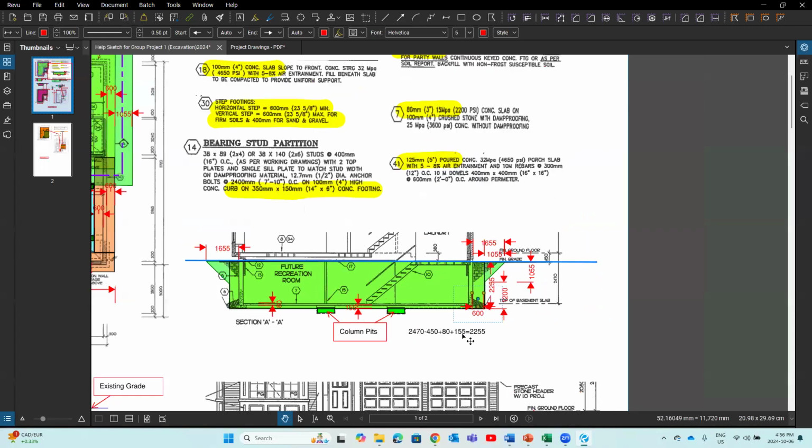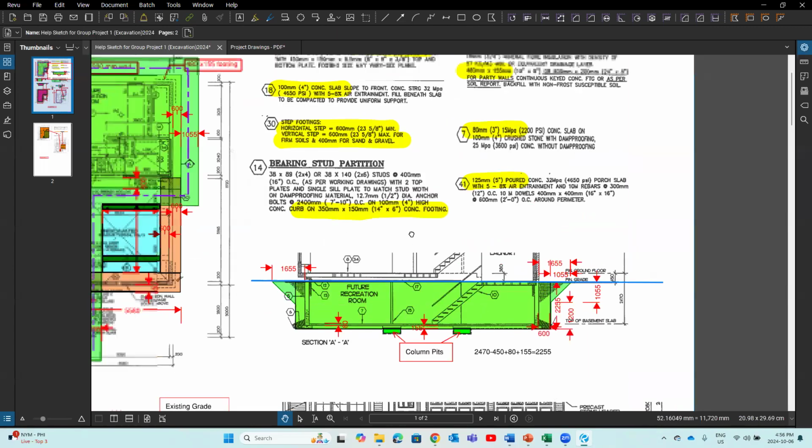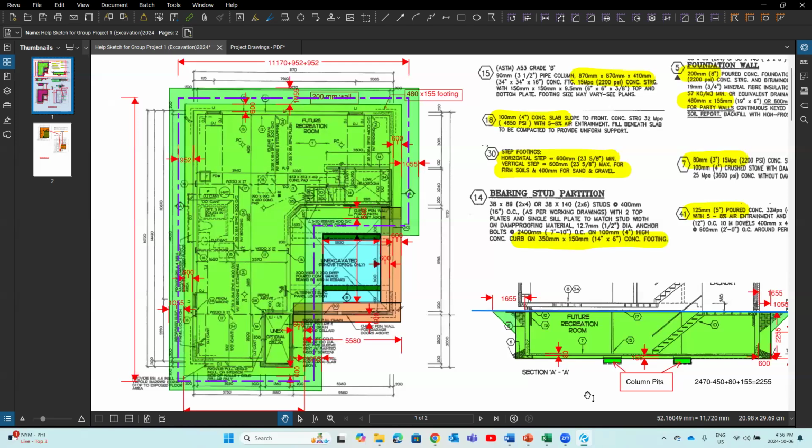After we finish this sketch, we are going to move this sketch to my foundation plan. In my example, I taught you the easiest way to do the excavation is to separate the volume of the basement excavation into 2 parts. The first part, we assume we are going to cut straight down. Say this green color. We excavate the basement from the existing grade straight down to the bottom. Then we add the volume of this slope, which is a triangle.